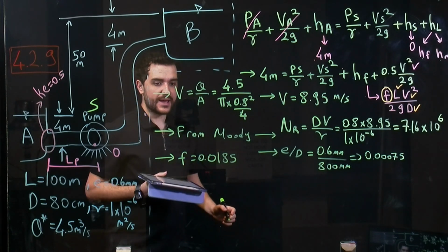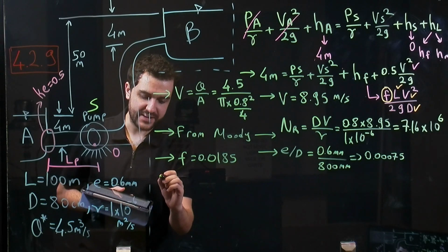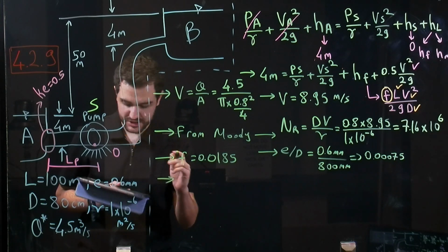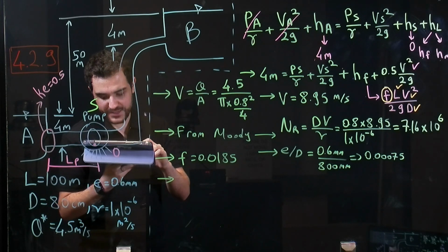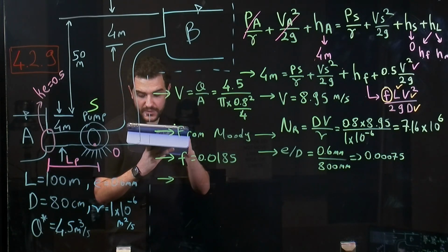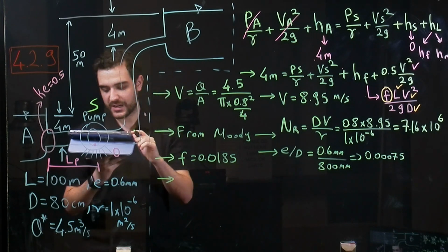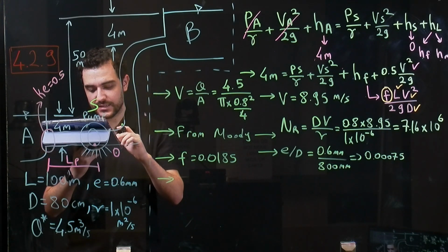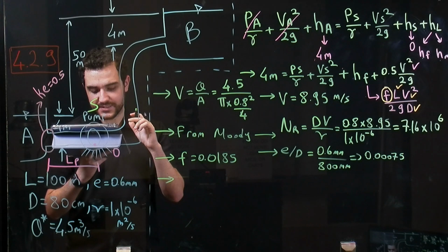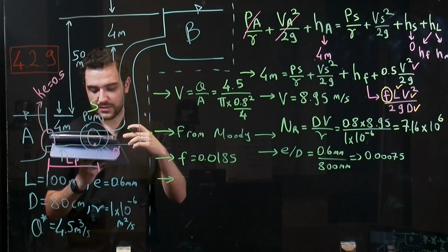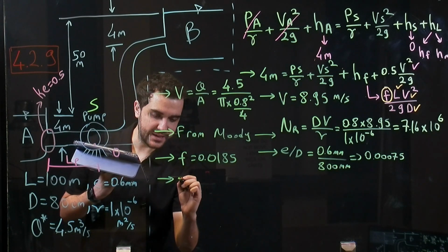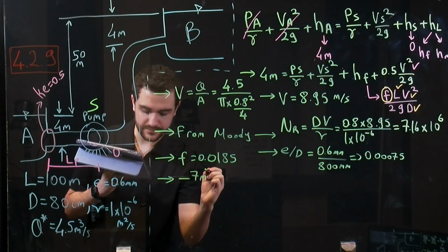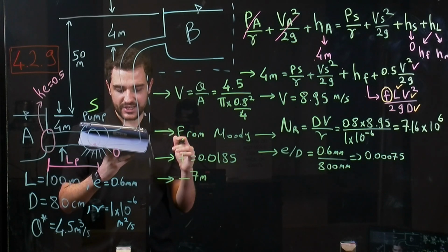Okay, and also from your textbook you will find information. So the information says that negative pressure should not be allowed to exceed approximately 2/3 of standard atmospheric pressure head, or it shouldn't exceed 8 meters for the cavitation.